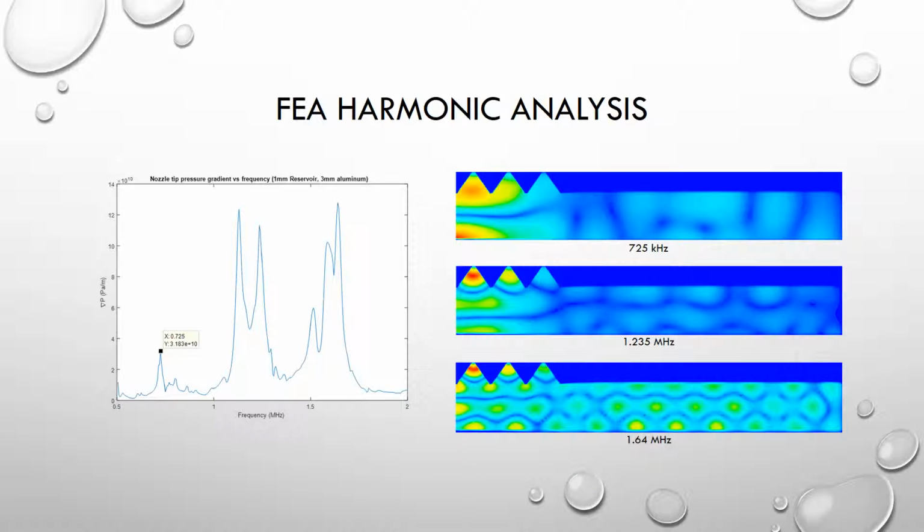Here we can see the time-averaged pressure amplitude of the 3 resonance modes within the fluid reservoir. The first mode corresponds to a half wavelength resonance, with dark blue corresponding to a pressure amplitude of 0, and the red corresponding to the maximum pressure amplitude, which is typically between 1 and 2 megapascals.